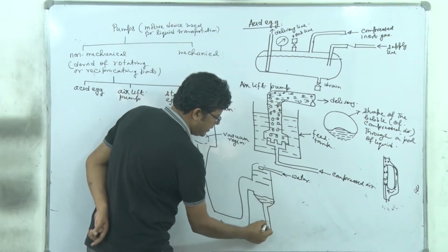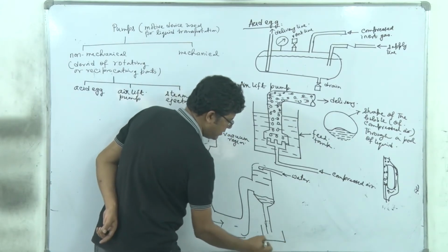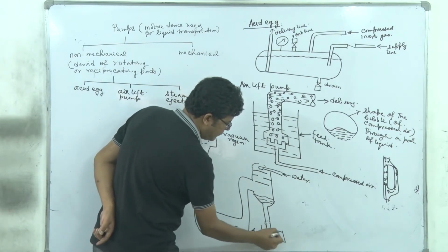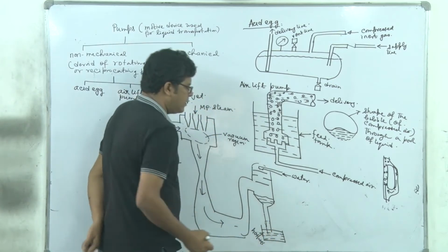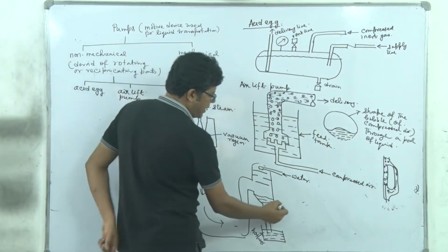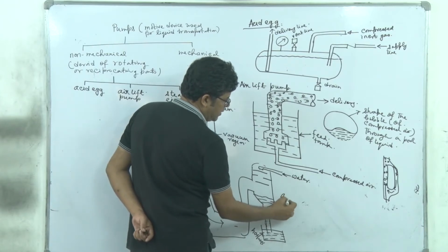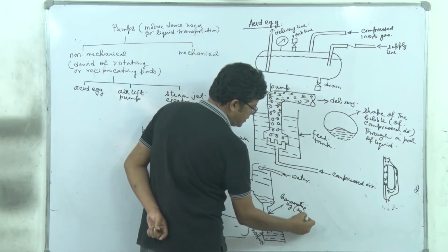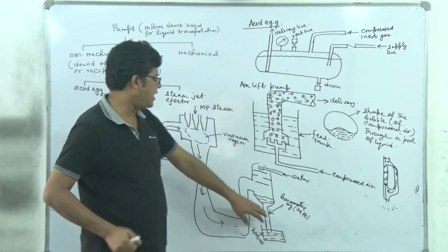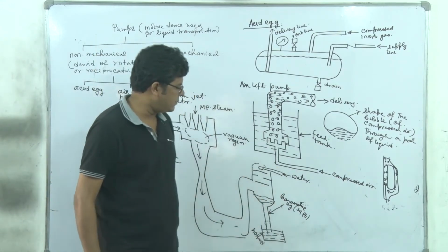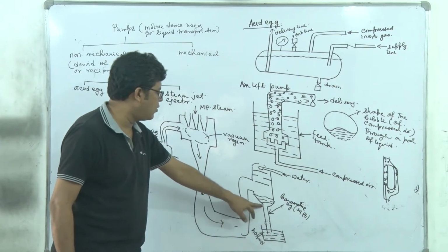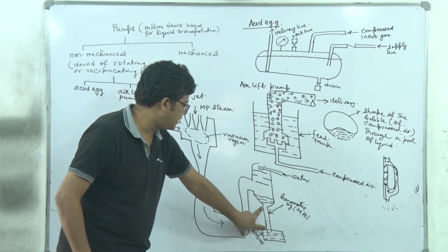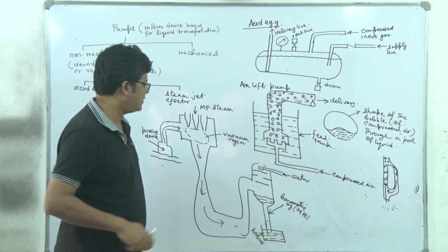The condensate is released in a tank at the ground called the hot well, which seals the vacuum. And this long tail pipe is called the barometric leg, and its height will be 34 feet. Why? Because here we have atmospheric pressure, so against absolute vacuum, we know that a water column can rise up to 34 feet. So if this barometric leg is 34 feet high, definitely there will be no back mixing.